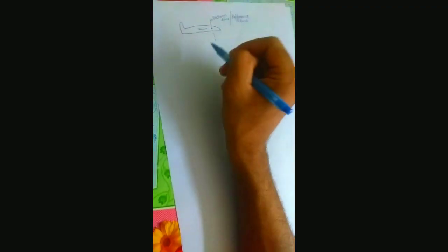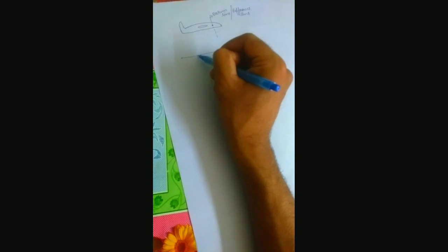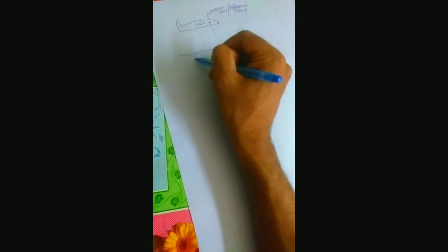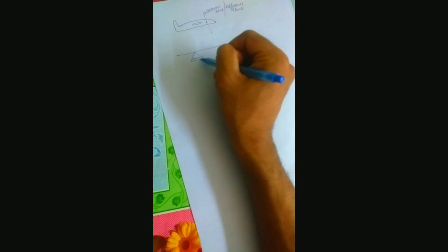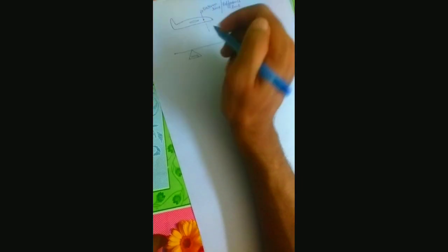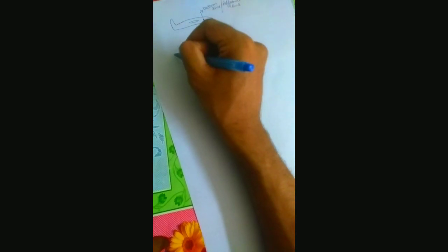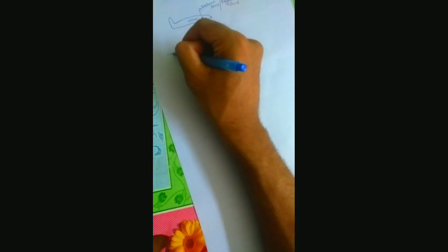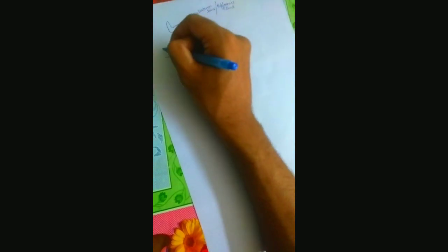Hi guys, in today's video I'll be talking about how to find the center of gravity of an aircraft. Now let's take the aircraft as a seesaw. Now the rectangle and the triangle which I have shown, I'll consider as a wing. Now the datum line which I'm drawing now is given by the aircraft manufacturers. Now to the right of the datum line I'll take it as positive, and to the left I'll take it